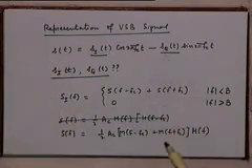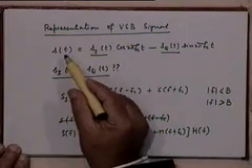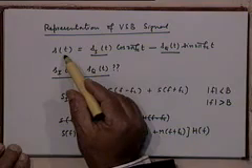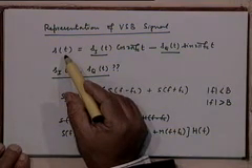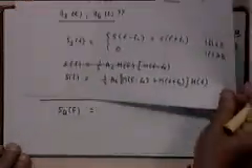And that will give us a relationship in the frequency domain also. How will you recover it? You multiply this with sin 2π fc t and pass the result to a low pass filter, right? So what will be the spectrum of s(t) sin 2π fc t? That's what you have to really see.